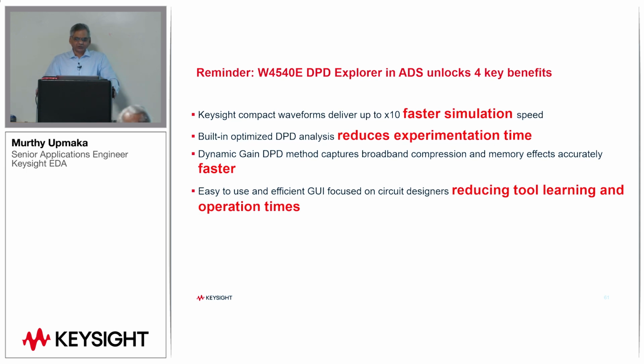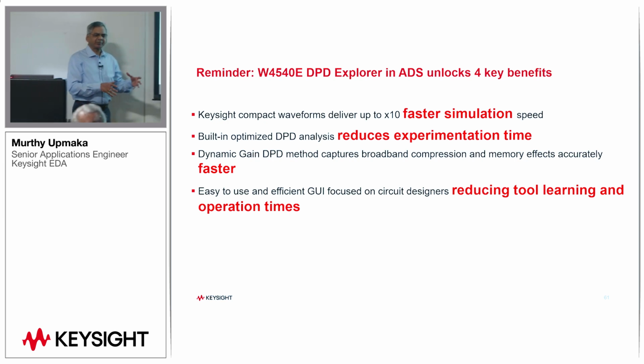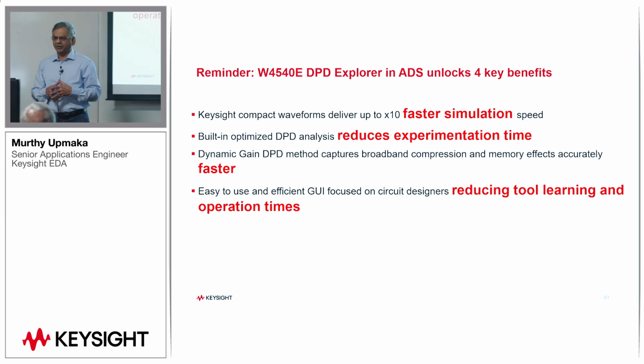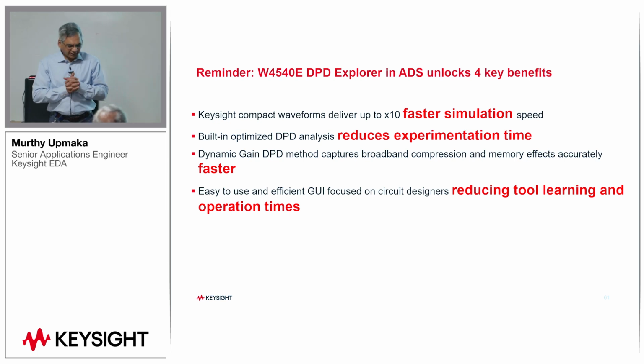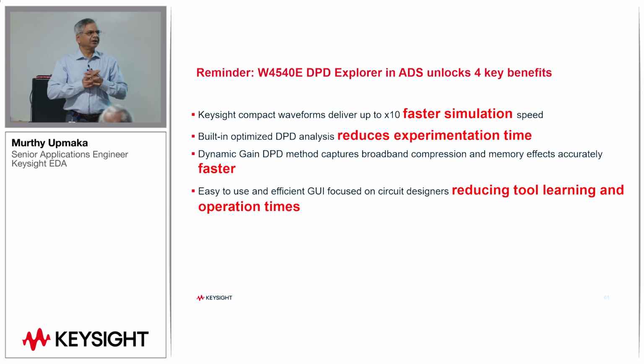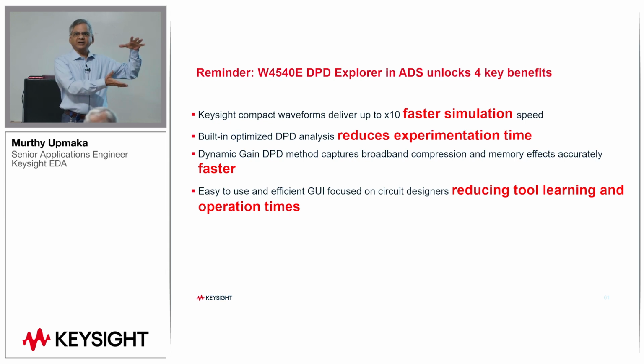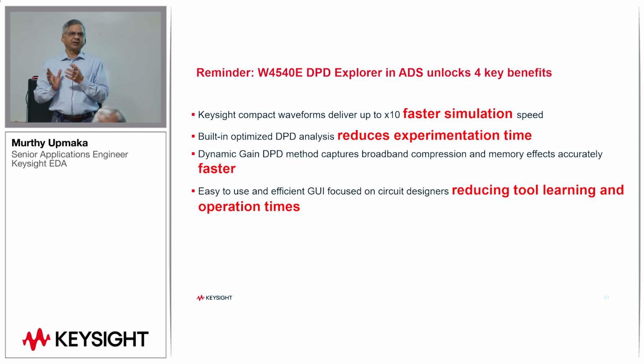So just to conclude, there are some aspects that are improved into this waveform. Any one of you have made any measurements or simulated, let's say, the EVM of an amplifier, with a very complex modulated, some kind of a 5G waveform, let us say. Measurement of EVM or CCDF is a statistical measurement, right? It's not that you just measure once and then it gives the final answer.